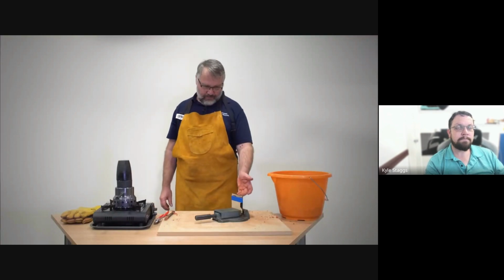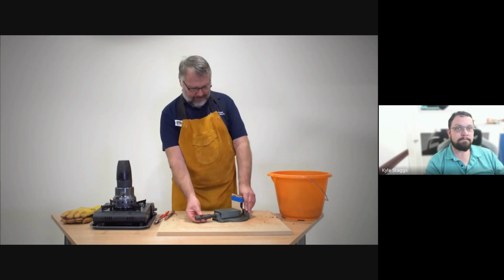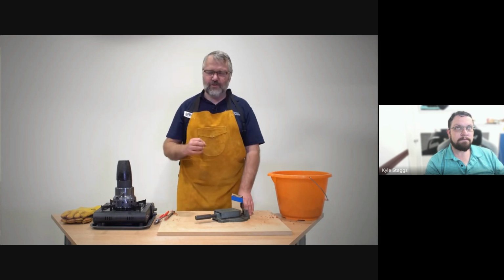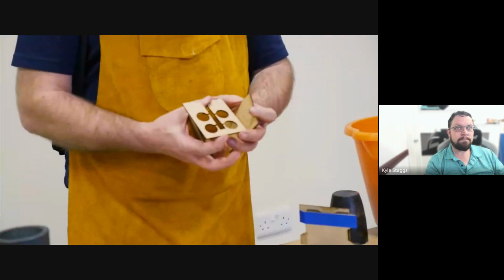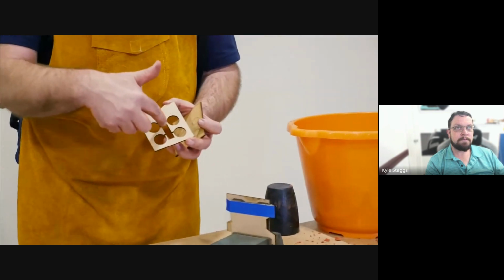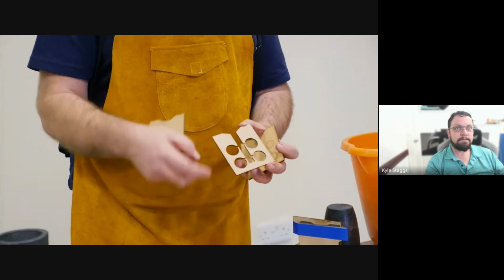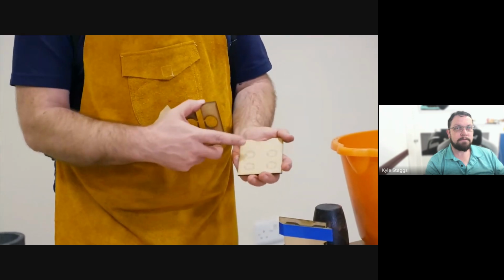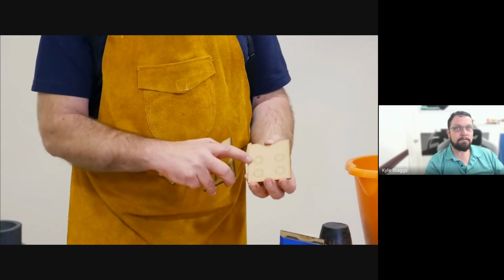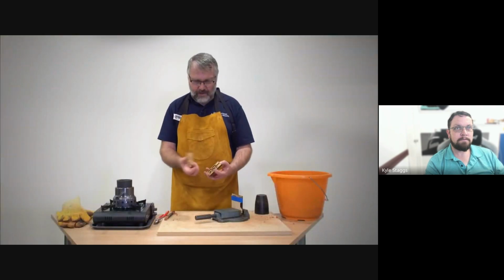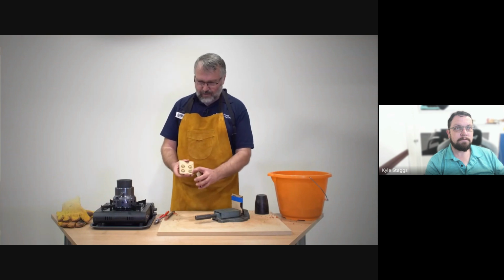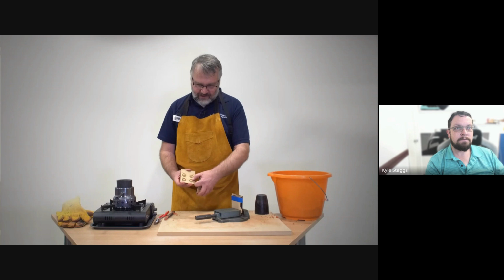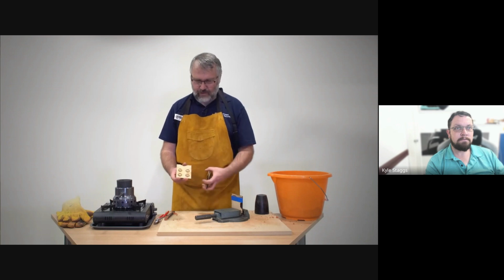This is a nice simple die made out of MDF laser cut to produce the supermarket shopping tokens. It can be produced out of MDF with a laser cutter, with a channel for the metal to form the shape of what you're doing. The two slices that go on the outside of the sandwich, one has got text, which has to be in mirror writing, and the other, in this case, has got a little shopping trolley logo, but there are vents to allow the air to escape as the metal runs in.